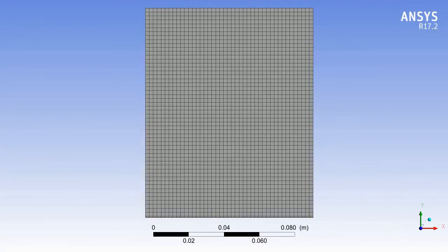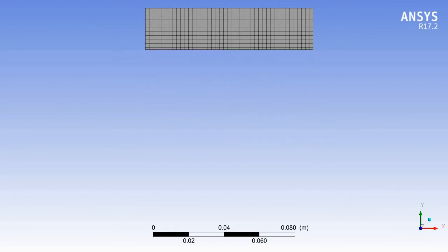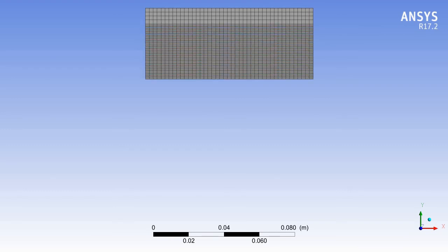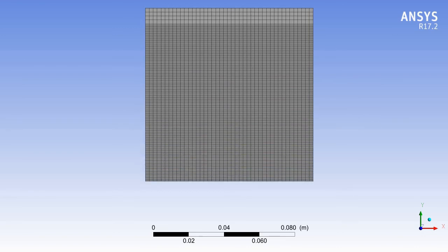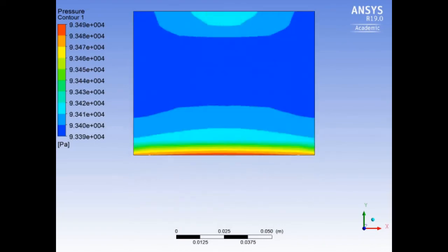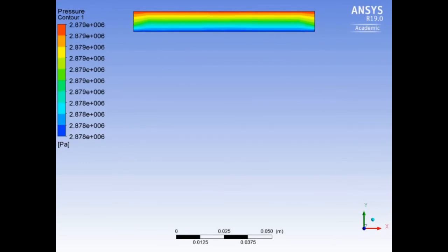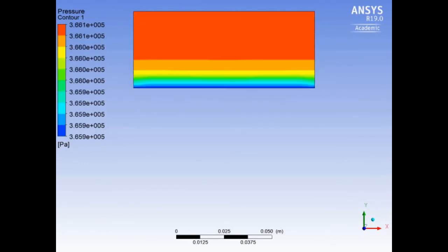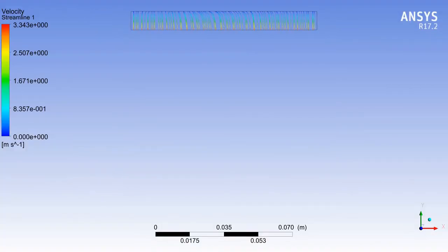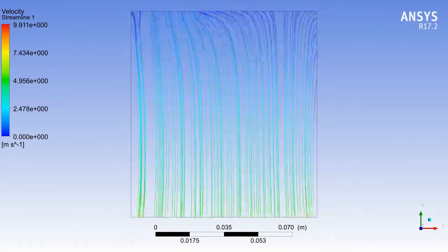So this is how, during the dynamic action of the piston, the mesh will deform and the piston will move in this way. So this is the dynamic deformation which you can incorporate via the dynamic mesh option. These are the pressure contours continuously changing during the dynamic mesh. When the piston moves in the upward direction, the higher pressure will be located at the top dead center, and these are the path lines which I captured during the suction stroke as well as the compression stroke.